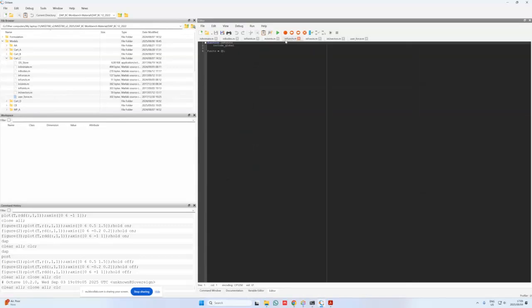Then in funct, in this case, is now going to be an open list, since we're doing a forward dynamic analysis. So we don't specify any driver constraints on the system. If we then look at in U vectors as well, this is also an open list, since we don't have any translational joints acting on the system. However, one of the files that have now changed is in forces.